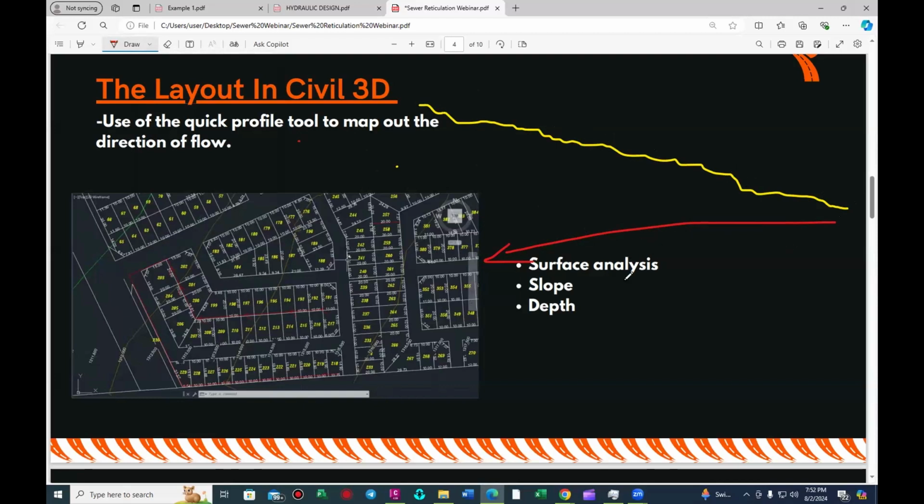And remember, your sewer line has to be at a certain slope as well. So we're saying there should be a slope difference here, right? There should be a change in that angle theta there so that your sewer can flow by gravity. But if I oppose my sewer like this, it simply means that I'm going to have to trench at very deep levels so that I can lay my pipe. This is very, very expensive.